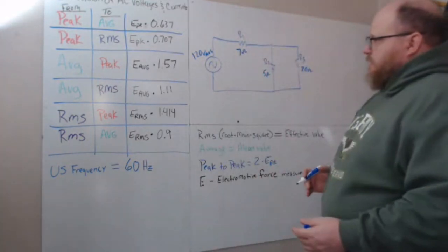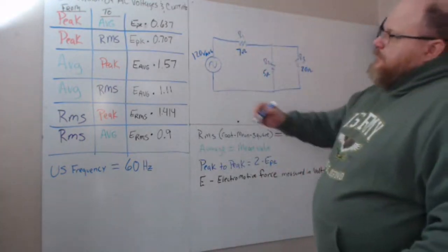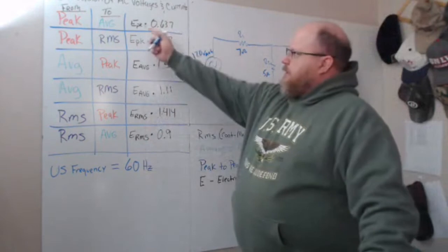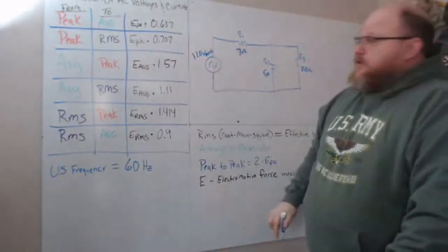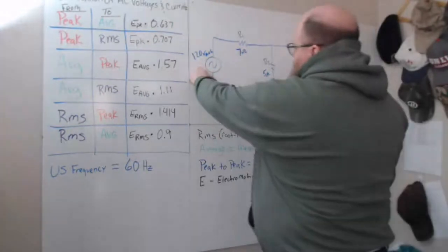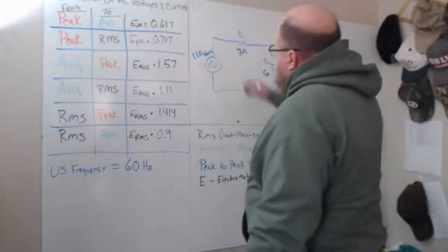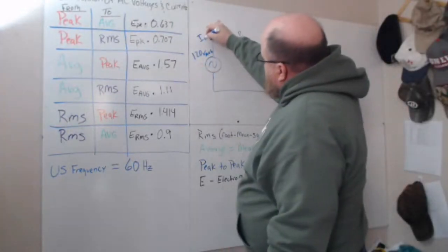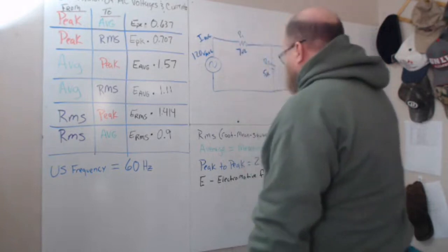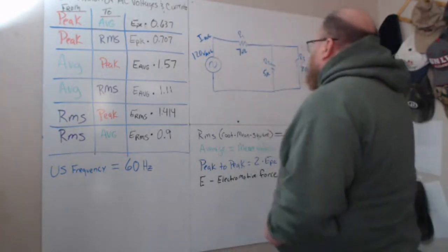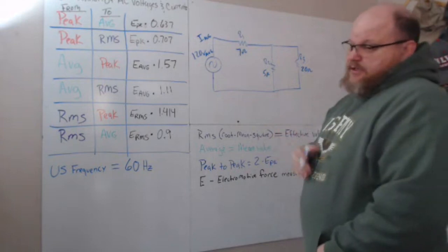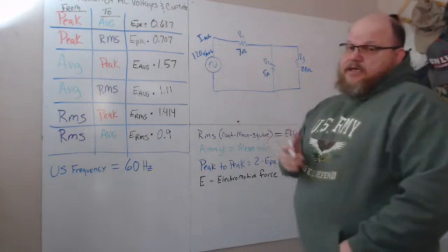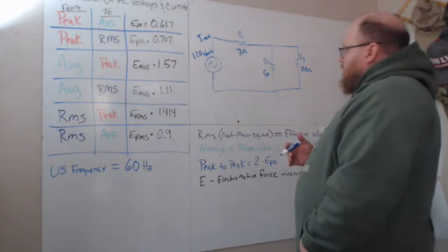So if I start with 120 volts average, and in here you can do this with current. It could be I peak, I average, I RMS, same multipliers. So if we solve for this, first thing we're gonna find is current average. Since this is a combination circuit, we have to use both the rules of a series circuit and the rules of a parallel circuit.